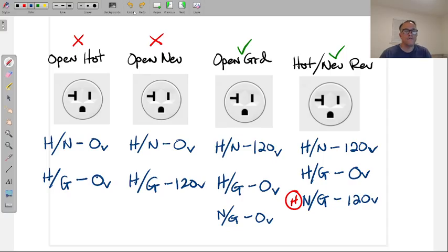The other reason why I like to open up the device is it gives me access to the actual little screws in there, and I'm an over tester. I overly confirm problems. I have seen too many weird things. For example, I'm measuring between the hot and the neutral inside the receptacle part, where the prongs go in, and I'm getting 0. I have seen receptacles simply be damaged, where I have power, but the receptacle's bad. So that's why I say never with 100% confidence on anything.